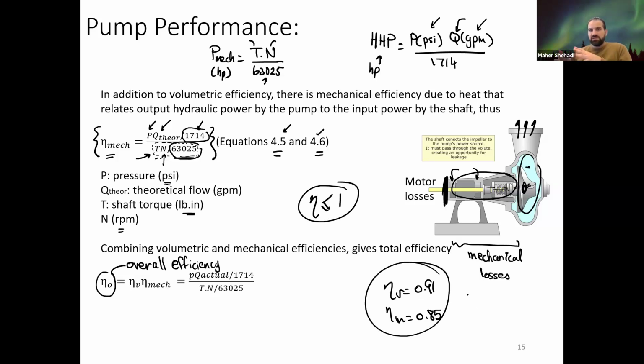What you should do is take the first one, the volumetric efficiency, and then that output is also going to be less due to friction losses by 15% from here. So the overall is actually the product of all the partial efficiencies. So if you have electric efficiency, then you add it here. If you have some other efficiencies, you just multiply by them. So you keep multiplying those efficiencies.